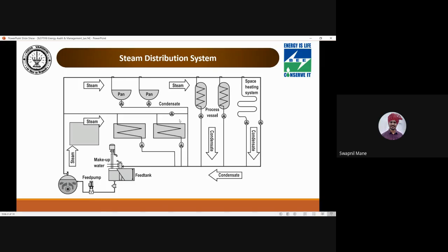Right. So what things are required at the design stage? The working pressure is a very important point. The distribution pressure of the steam is influenced by a number of factors, for example, the safe working pressure of the boiler. We cannot keep it too high or too low.